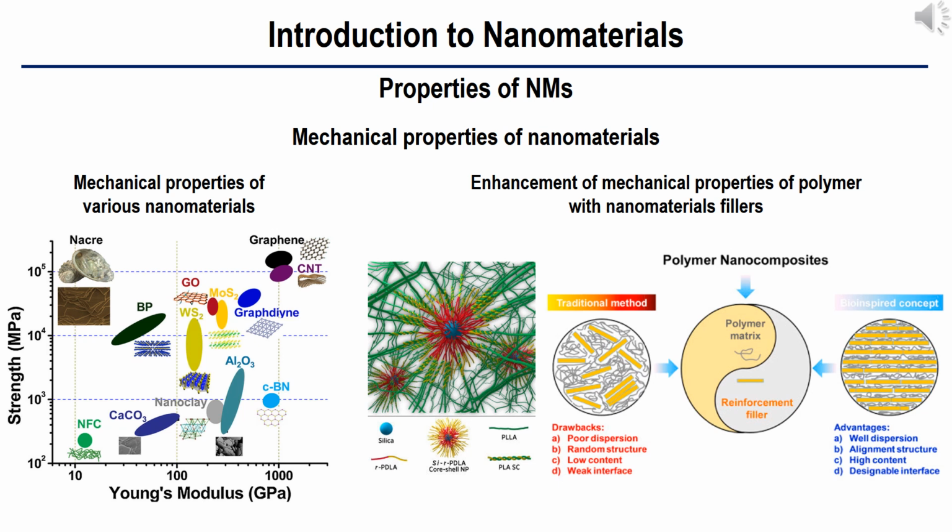Therefore, model calculations and molecular dynamics studies are of major importance for an understanding of the mechanical properties of these materials. Good mechanical properties of nanomaterials can be applied to produce tough and flexible materials. For example, filling polymers with nanoparticles or nanorods and nanotubes, respectively, leads to significant improvements in their mechanical properties. Such improvements depend heavily on the type of the filler and the way in which the filling is conducted.